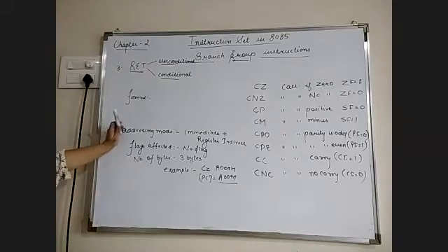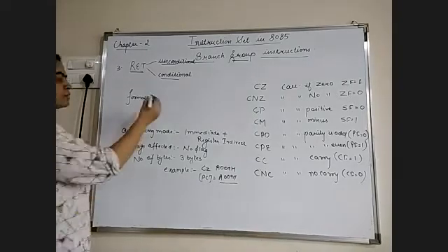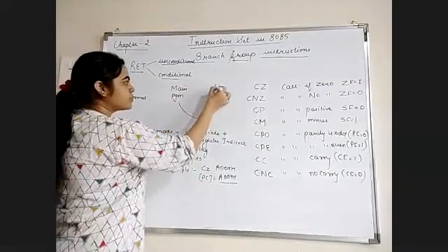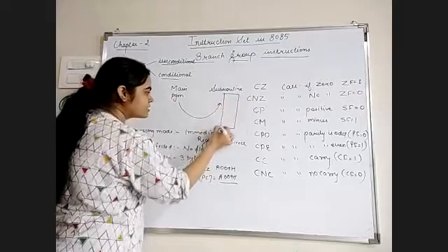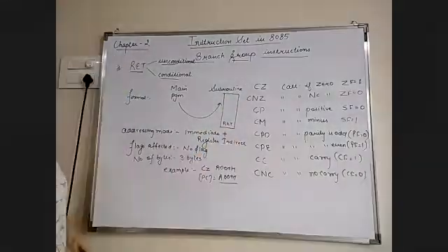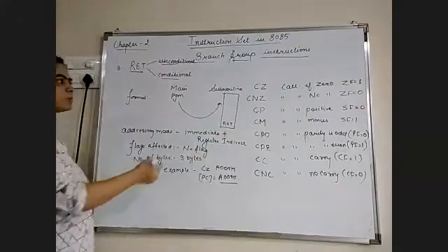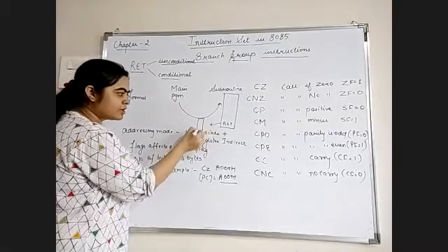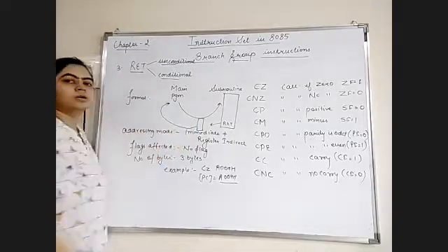So this instruction works with the help of the call statement. When this instruction is executed, the program counter is transferred from the subroutine program to the main program. That means during the call operation from the main program, the microprocessor jumps to the subroutine program, and in this subroutine program we have an instruction at the last, that is the return statement. Once this instruction is executed by the microprocessor, it will get back from the subroutine to the main program. But before this, it will come to the stack memory, pop out the contents of the program counter, then jump to the memory location in the main program.